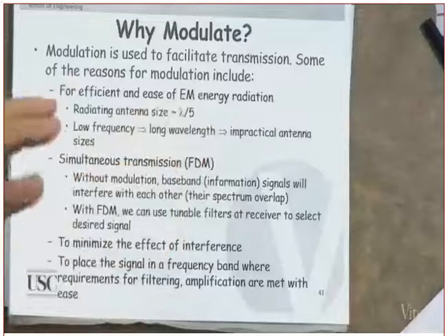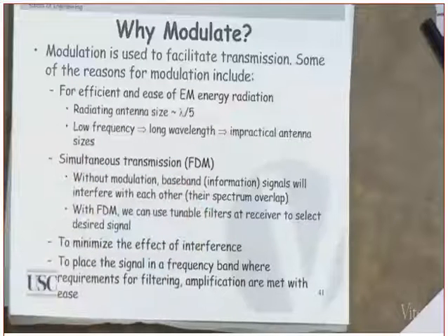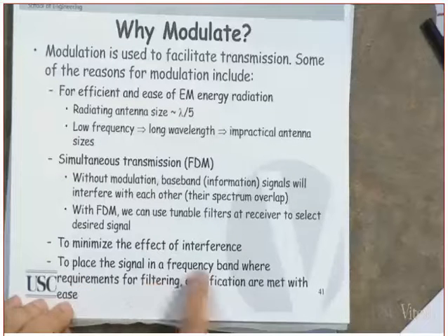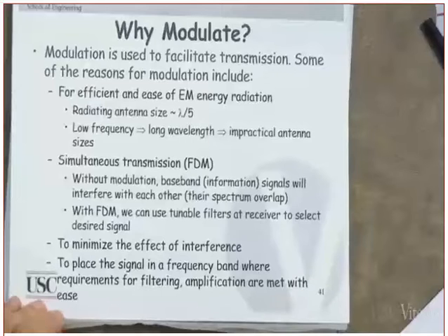With modulation, what are you doing? You are leaving that band which is noisy, and operating in a larger band or higher band, yes? And then after you receive it, you can return it to the original band. Clear? Okay. Again, sometimes you need to place the signal in a frequency band where the requirements for filtering and amplification are met with ease.